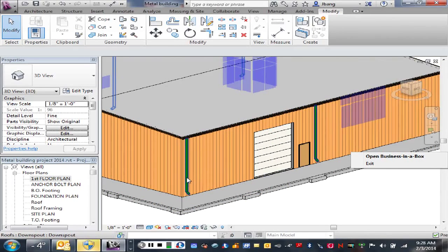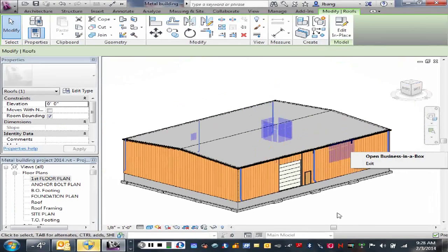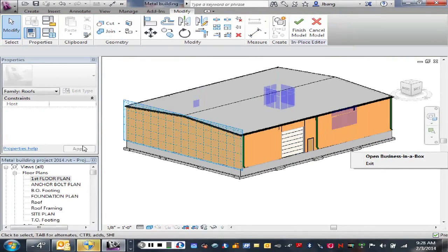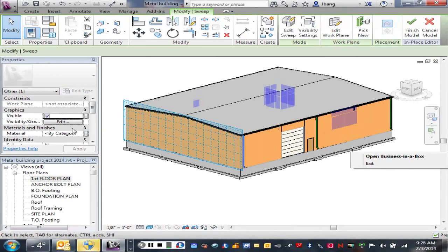So in this case, I'm going to select those downspouts, and you'll notice because I didn't finish after I completed one, I did all that mirroring before I finished. They're all one unit. All 6 of those are one thing. And I can go to Edit in Place and select again and go change the material on them.